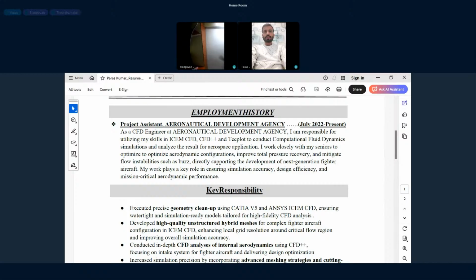Then what else? Swirling and other instability. It will be related, no? Pulse is also not there, sir. When you calculate the distortion coefficient, wherever swirling is there, it will come out. Normally, for the aircraft engine, anybody specifies swirling and all those things, they will specify distortion only. Yes, sir. I see. So those are all sub parts of that. Only distortion coefficient, pressure recovery.